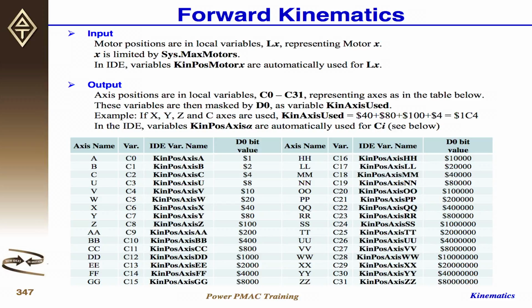It's ldata.status. If it's equal to 1, that means the forward kinematics is called by a motion program, which is usually the case when you execute a motion program. The second one is if it's 0, then it's being called by a query command. That's an online command that I listed here. Okay. How do we use this? With this bit, you can actually abort the program properly, which I'll explain later.